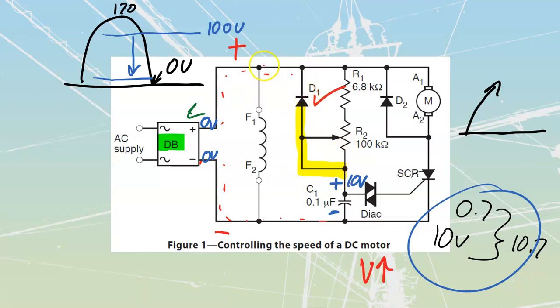And then I've got a cathode, and then I've got my electrons, which can go somewhere. Where are they going to go? They're not going to go through the supply. They're not going to travel through here because this is going to send them back to themselves. They're not interested in that. They could possibly go through here, except for the fact that this SCR has shut off, which means there's really only one path left, and that is they go through this field that we are going to have.